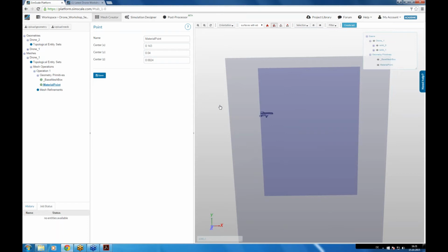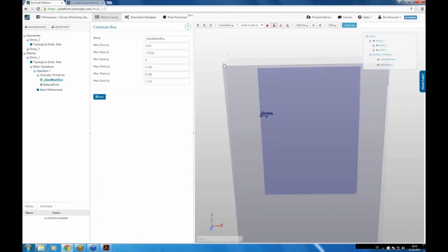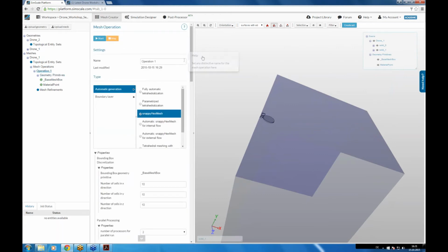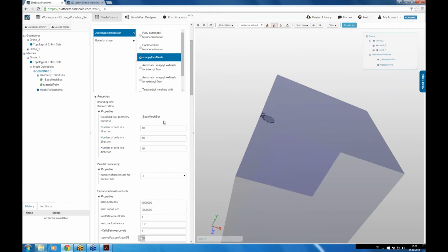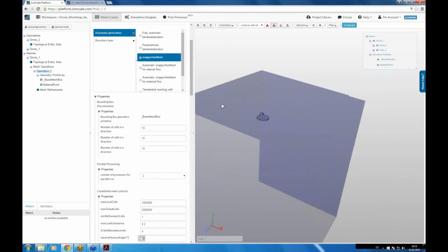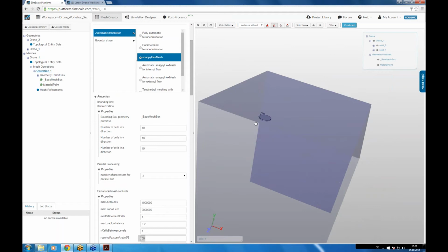Okay, and now we can start, basically. And the first thing we will do, if you look again here, is define the so-called base bounding box mesh size. So we have to define how big the elements of the mesh should be here, because SnappyHexMesh is working with a base mesh size, and then you're adding local refinement, and so that's the largest mesh size we will use.